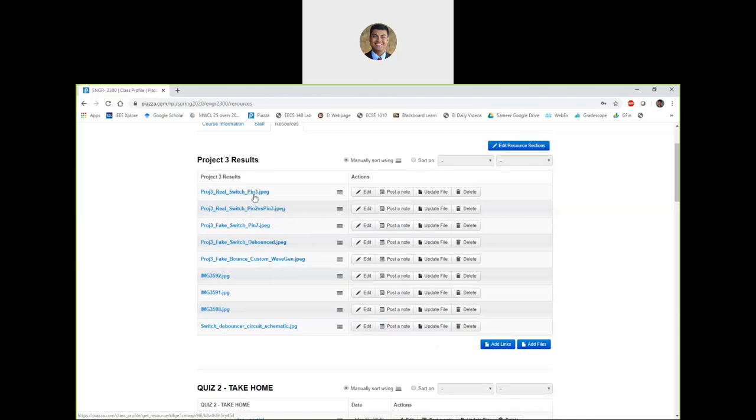Now, today I'm going to look at circuit 2. So I'll change those values from 10k to 100k to 10k, and I will change C1 from 1 microfarad to 10 microfarad, and do that same experiment again. I don't think there is any point showing you guys how to do that. It's just a simple component swap and run the experiment. So I'll just upload those results.